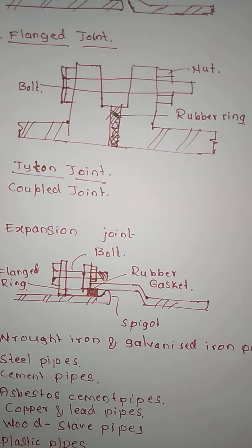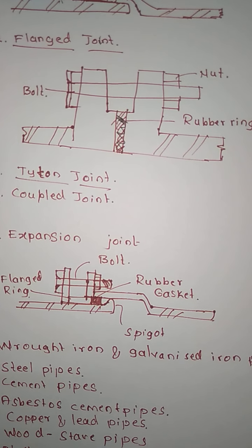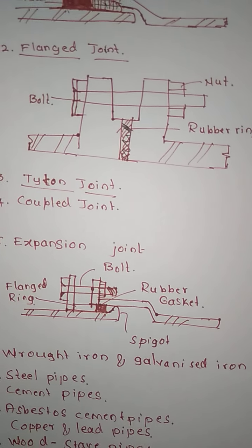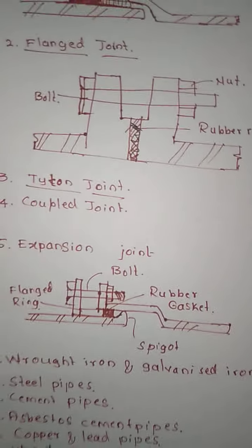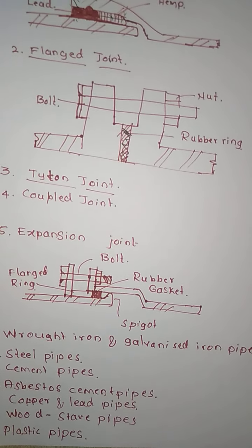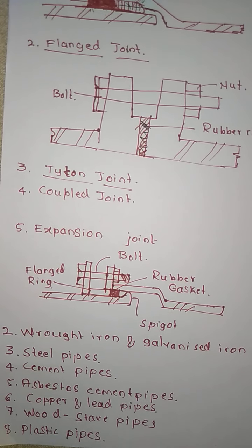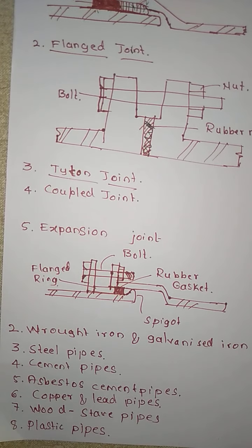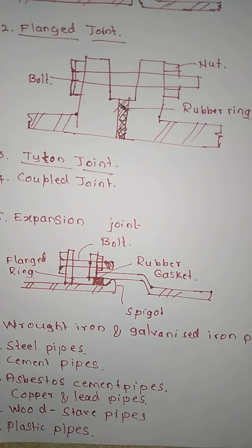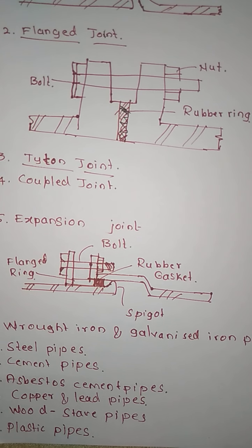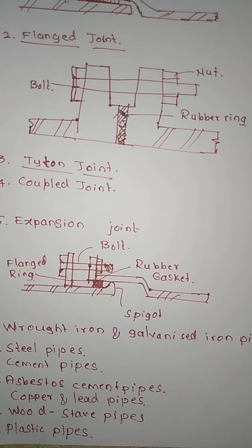Now we will see what advantages these concrete pipes have. As these are concrete pipes, the maintenance cost is low. They are more suitable to resist external loads. Third, the inside surface of the pipes can be made smooth, reducing frictional losses, and the problem of corrosion which was there in the case of cast iron pipes is not there.